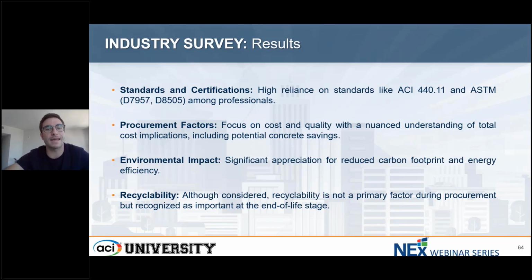And finally, last point, recyclability. We saw that the industry didn't feel it was a big deal. The recyclability of FRP meshes right now is not fully understood, in the sense that there's a big benefit: you can crush your FRP with the concrete and use it as recycled aggregate, and you don't need to differentiate the reinforcement and concrete as you need to do with steel.